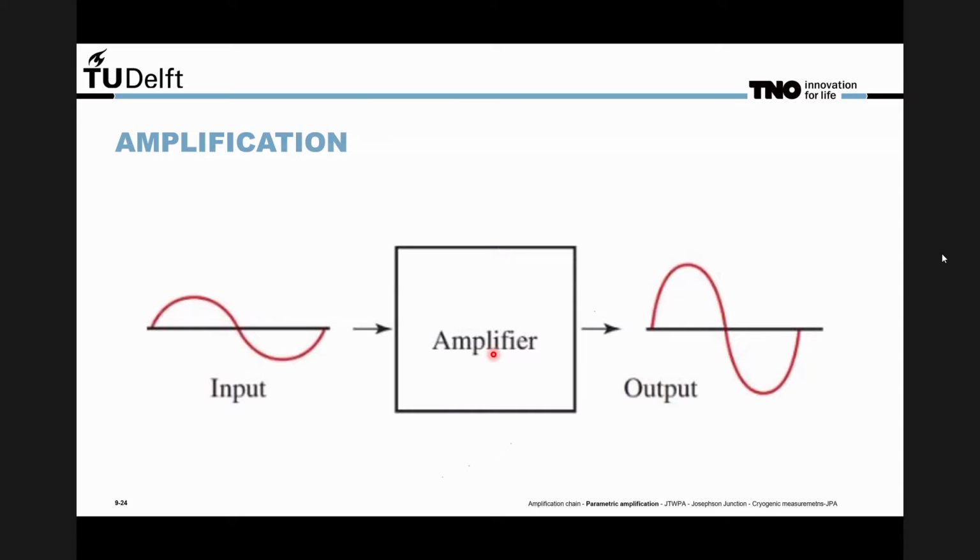So the difference between the input and the output signal amplitude is called the gain. And this can also be seen as the ratio of the output to input power. And this is usually measured in decibels, which is a logarithmic scale of the power ratio. Lastly, amplifiers also add some noise in the system. Noise is an unwanted but unavoidable effect that creates disturbance in the desired signal.